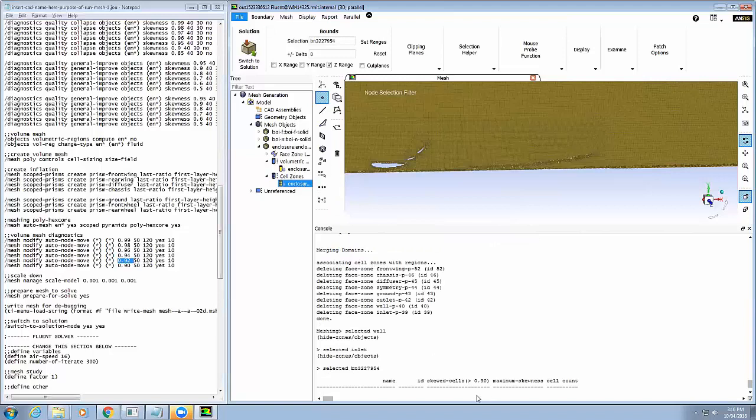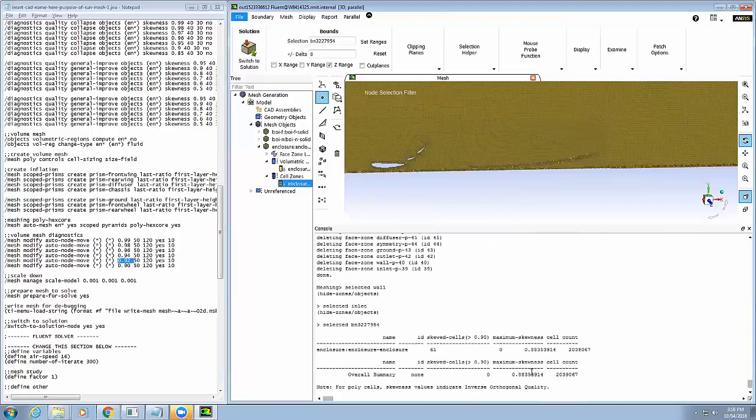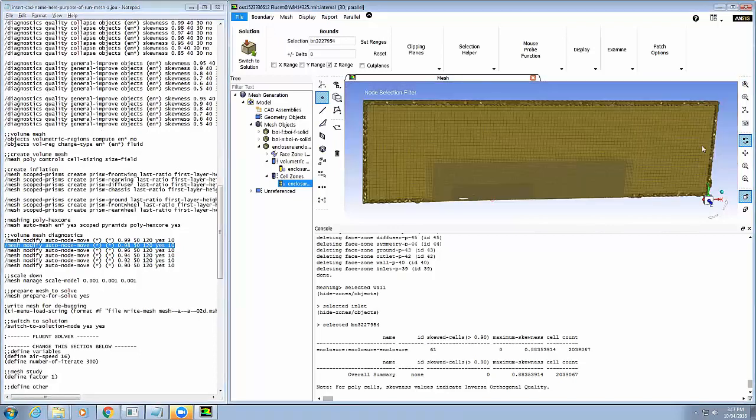So if I just go summary, you can see, cool, that's actually a really good cell count. That's a good cell count because I don't have inflation on everything. As soon as you inflate everything, it just causes errors. Well, it can cause errors if you have bad geometry, and normally everyone has bad geometry. Fluent can have a bit of difficulty with inflation as well. Is that correct?